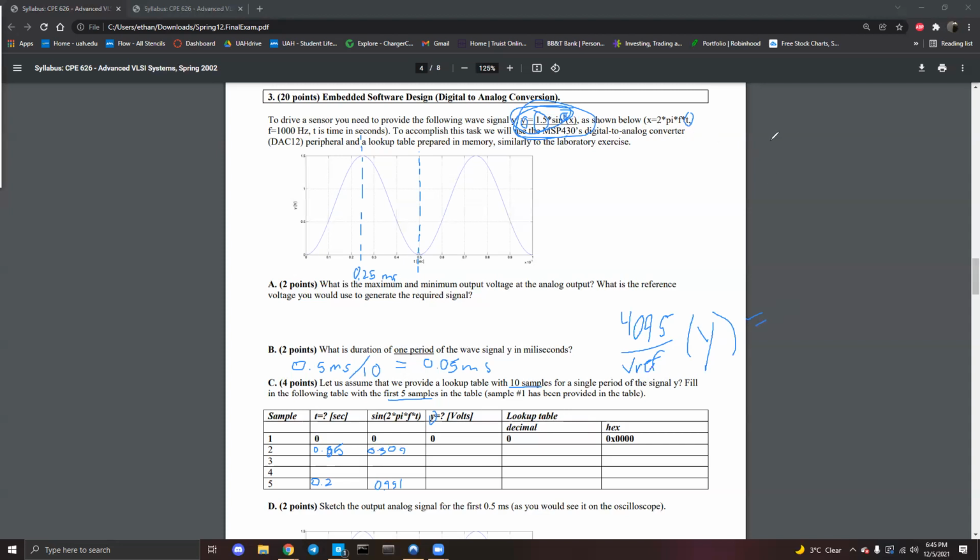The full one is the nearest integer of the value. In parentheses 2^n minus 1, which is where you get the 4095 because it's 2 to the 12 minus 1. And then that times the fraction on top being your ADCN minus your VR minus, and then over VR plus minus VR minus. Since VR minus in this case is 0, it's ignored. But for what it's worth, that is the entire equation.